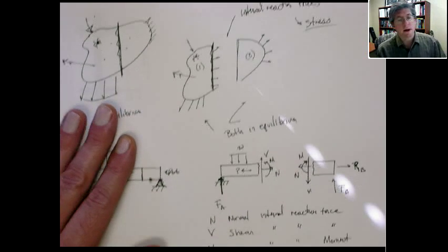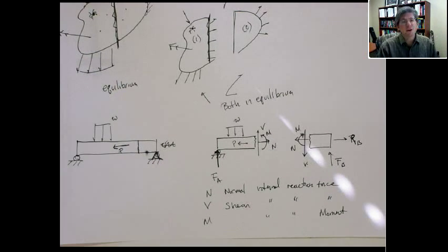The book also talks about internal reaction torques. The units of moment and torque are the same, and the way you decide whether something's a torque or a moment, you have to consider the geometry. Technically, they're the same. The units are the same. They're both the moment arm crossed with the force vector. But they have a little different connotation.